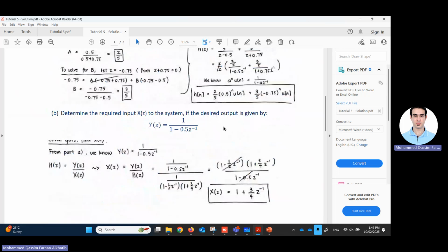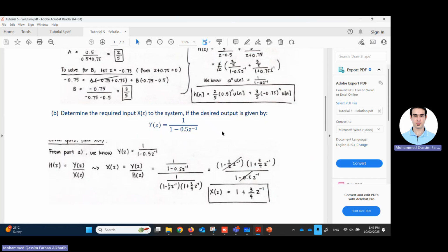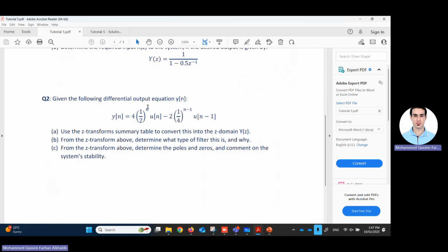Again, I will upload this one later, God willing. How is it an IIR filter? Because of the mathematical expression formula. If it were FIR, it would have coefficients 1, 2, 3, a finite number of components. Here, if you look at it even in the time domain, for any value of n there could be a value for the filter, so it's infinite, goes forever.